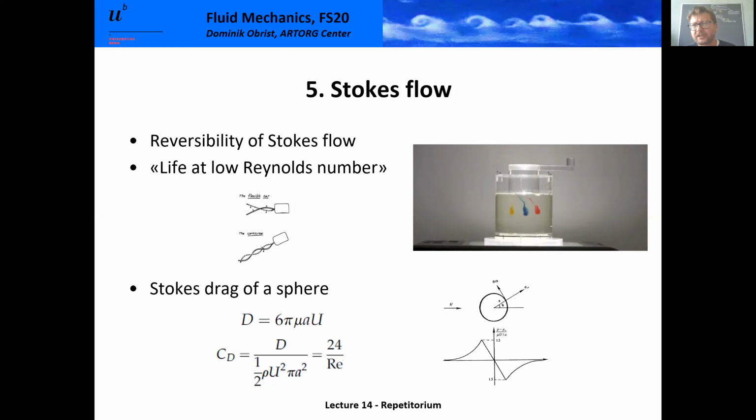These aerosol particles are actually little droplets, little spheres floating in air, and they adhere to the laws of Stokes drag. Whether they fall or settle or do not settle, how they are transported is governed by this simple law, D equals 6 pi times mu times a times U.